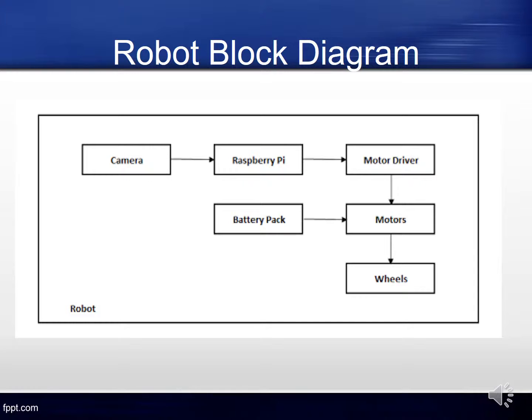The module uses the OpenCV library to perform Hough transform and Canny edge detection. The code is developed in Python, and the model provides signals of varying magnitude and direction to the Pololu motor driver. The motor driver then supplies the power to both the DC motors. The DC motors are supplied power by using 4 AA batteries connected in series. The motors are physically connected to the wheels.